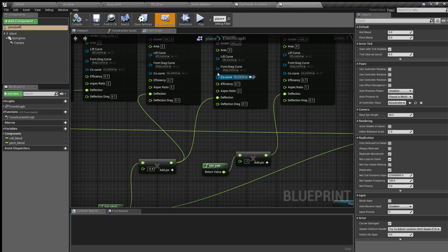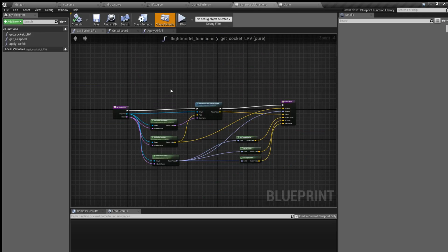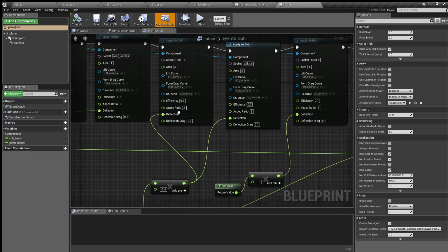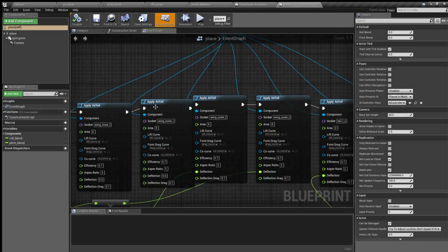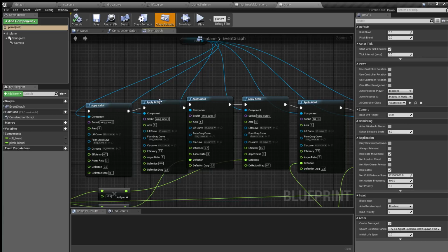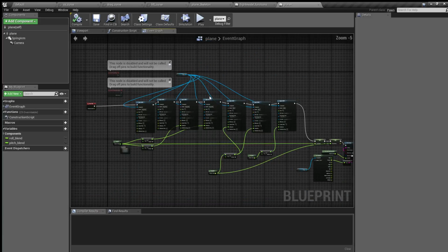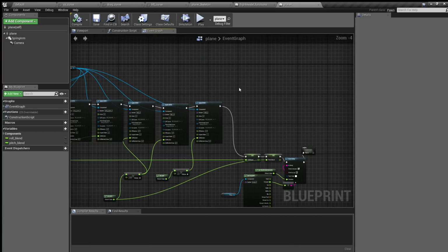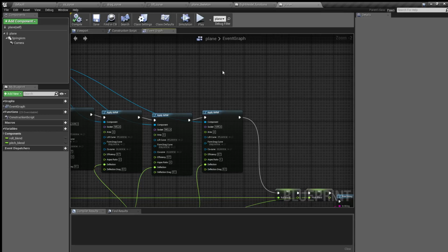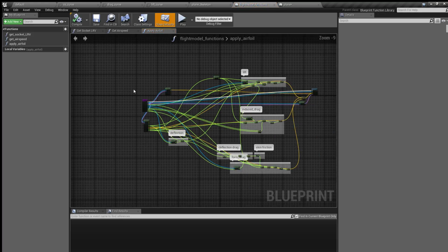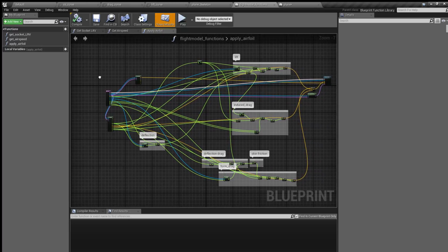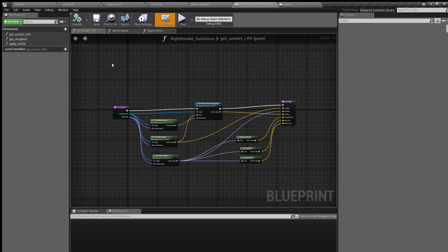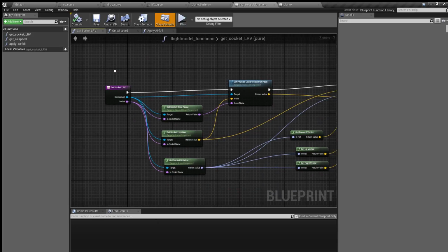Okay, so at each point, I'm calculating forces acting on the airfoil and then just using Unreal Engine's built-in physics to integrate those forces. And here's the blueprint. It's a bit of a clusterfuck, but I'll try to explain what it does step by step.